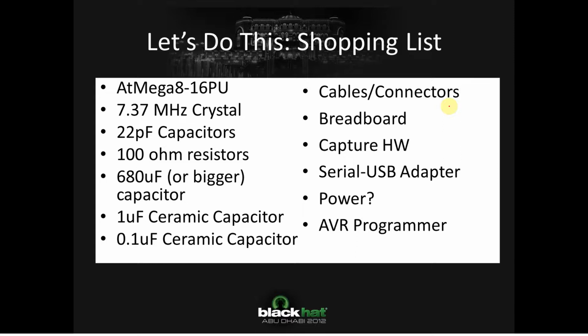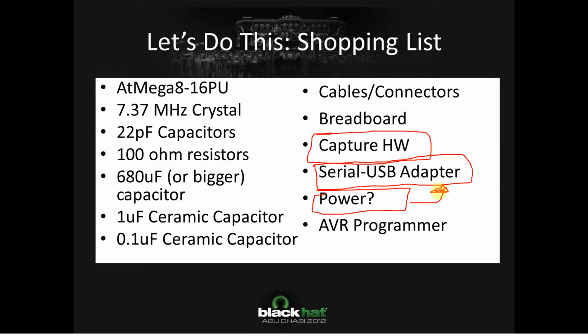The main thing you need is the capture hardware, typically an oscilloscope, but I'll show you some cheaper options. A serial USB adapter. You need a clean power supply, which I cheat and take from USB, which isn't too clean, but I show you how you can use that. And the final thing you need is a way of programming the microcontroller of your choice. I'm using AVR.